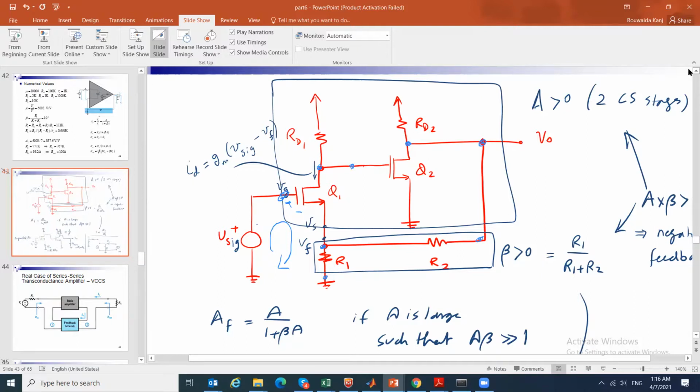If we want to look at this circuit, first let me explore what is the beta block. The beta block is the same beta block which we drew before, which is R2, R1. And so if we want to really understand what's going to happen in this circuit, we will end up removing the beta block from here and here, and drawing in parallel to the output node the resistance R22, and drawing in series with this node the resistance R11.